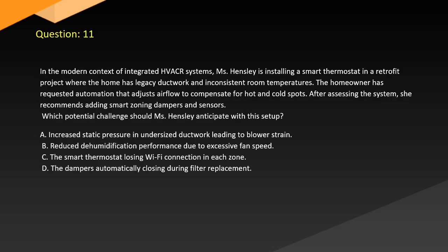Question 11. In a modern context of integrated HVACR systems, Hensley is installing a smart thermostat in a retrofit project where the home has legacy ductwork and inconsistent room temperatures. The homeowner has requested automation that adjusts airflow to compensate for hot and cold spots. After assessing the system, she recommends adding smart zoning dampers and sensors. Which potential challenge should Hensley anticipate with this setup? A. Increased static pressure and undersized ductwork leading to blower strain. B. Reduced dehumidification performance due to excessive fan speed. C. The smart thermostat losing Wi-Fi connection in each zone. D. The dampers automatically closing during filter replacement.